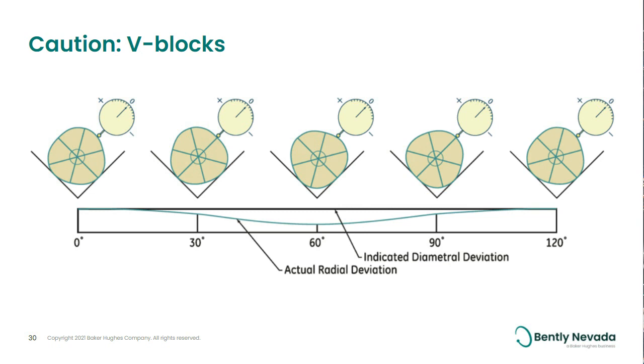And as a quick reminder, do not measure the runout in the same lathe that the machining was done, because any errors induced in that machining will not show up in the runout measurement if you use the same machine.